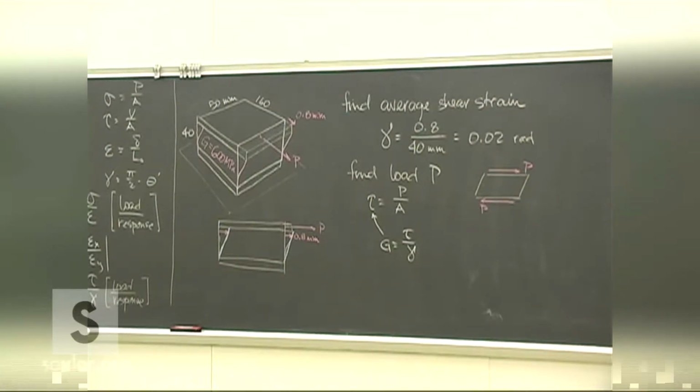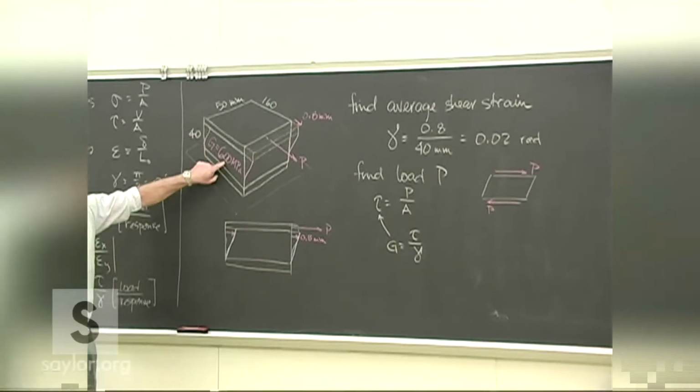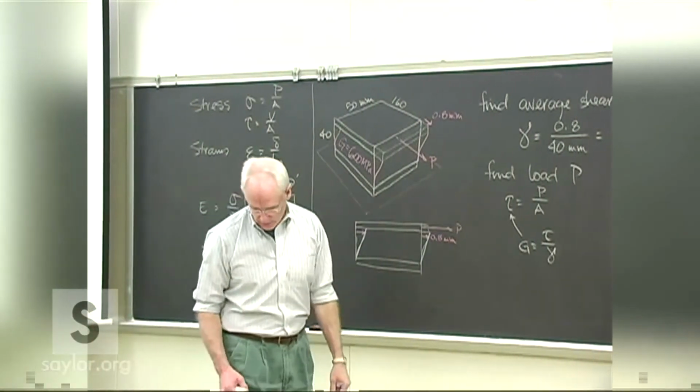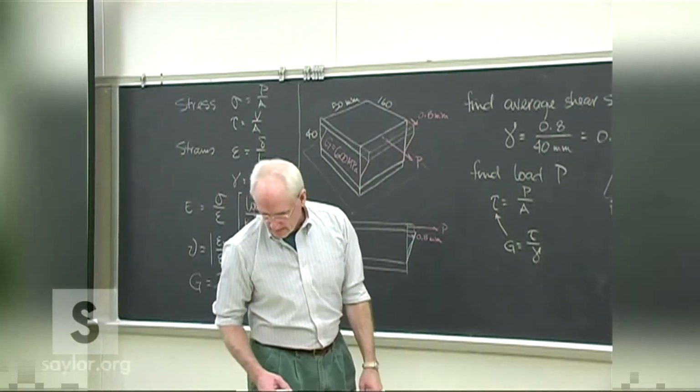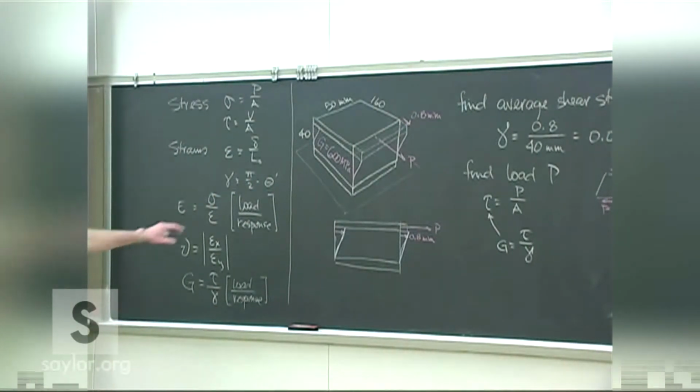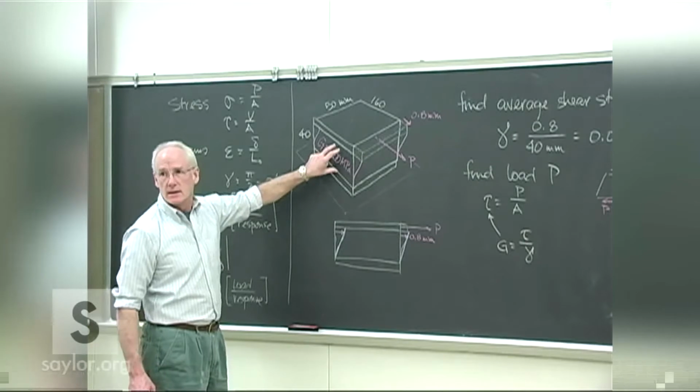Don't carry too many sig figs. Remember, we're going to have a huge factor of safety on all this, too. Everything here is based upon experimental values. Notice that this was a big round number, 600. So to take the answer to any considerable precision doesn't really match what you've got going in. You've got pretty approximate numbers going in. It would be unnecessary.